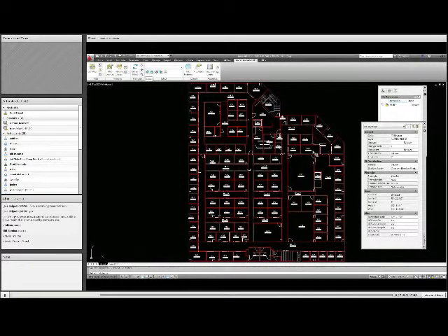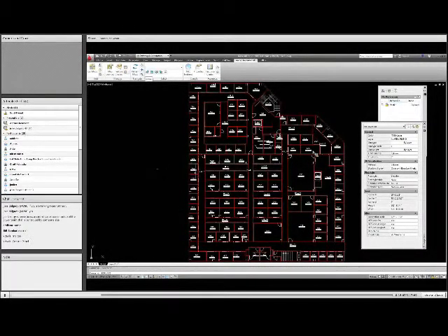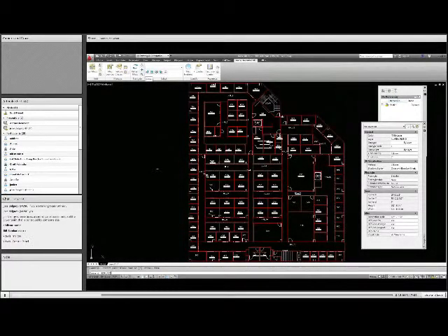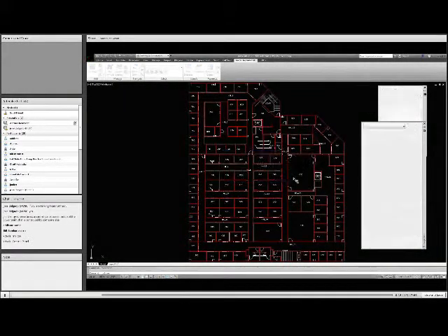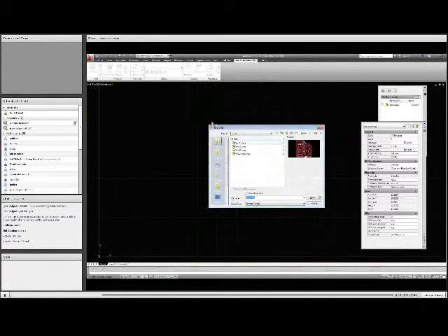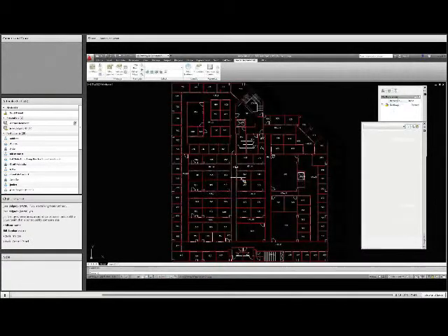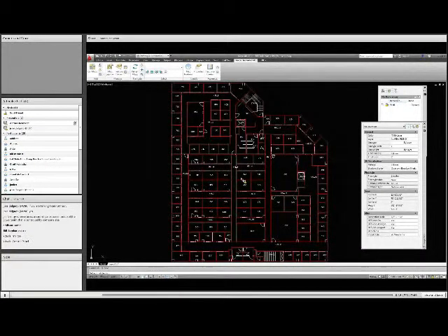So the error checking again doesn't actually do anything with the feature classes, but when I try to save the drawing, it actually does a lot more than just save. It interrupts the save command, does an error check. If there's errors, it'll present a hard fault. So if I try and save it again, it'll give me this error that'll be really clear to the user that they need to fix it before they go on. And save it again, everything's good.